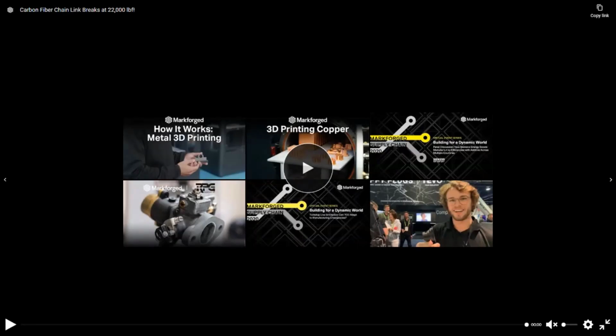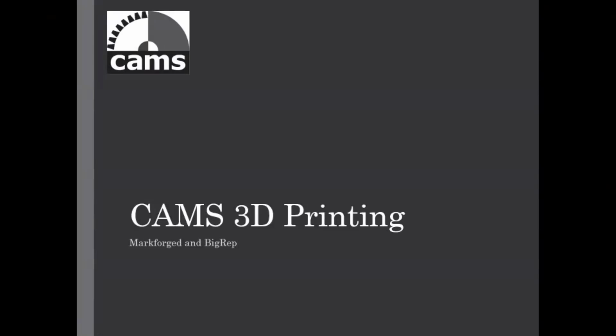Thanks, Brian. Question number 2. For the probing, does the post-processor need to be modified? That's a real big one. Yes. They've done a great job developing on the software side, and that's out and growing. And so, yes, the post-processor must be modified. That obviously takes time because every machine controller on the market can do probing differently and call different routines and macros. So yes, that also has to be developed through all the different posts and all the different controllers. But yes, the post-processor must be modified for that. So a post-processor enhancement needs to be evaluated and discussed.